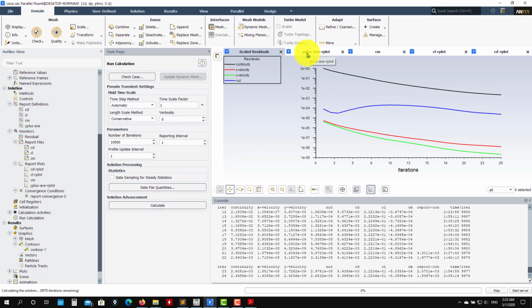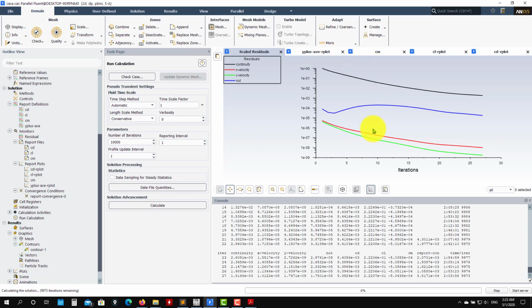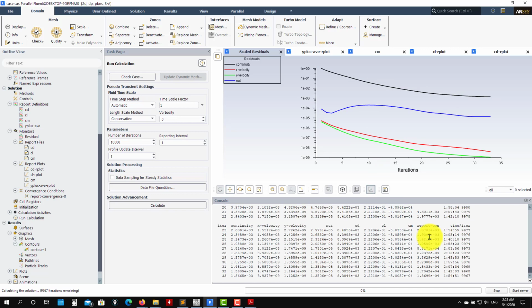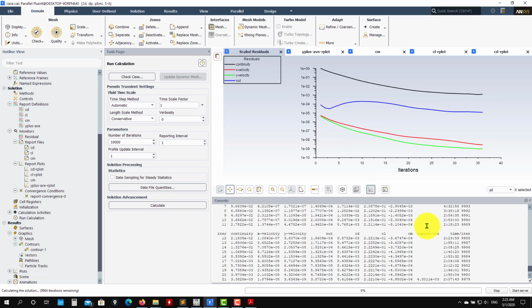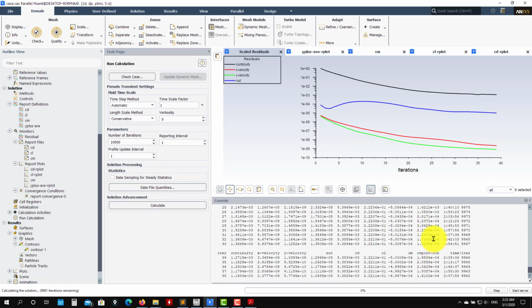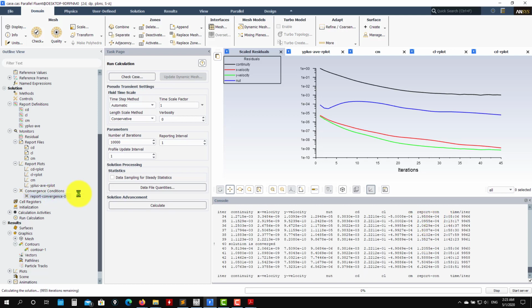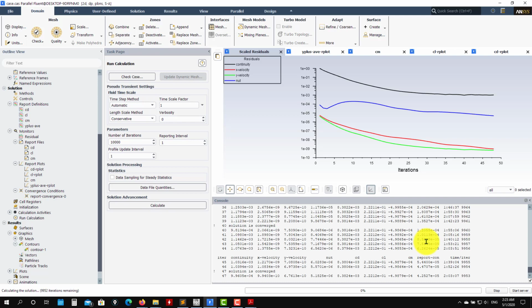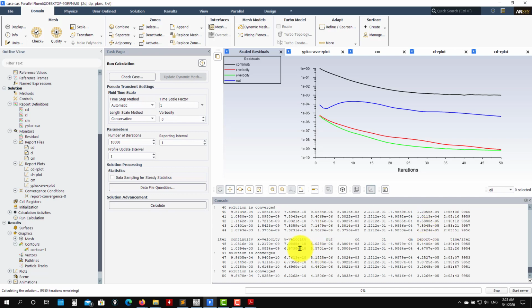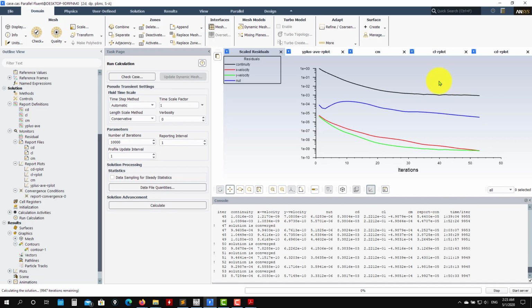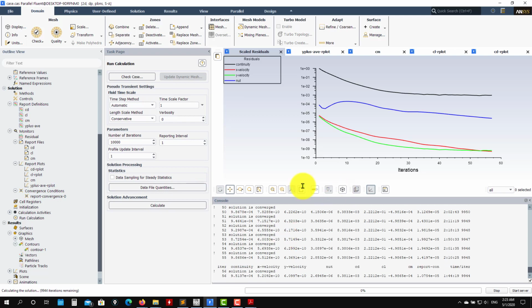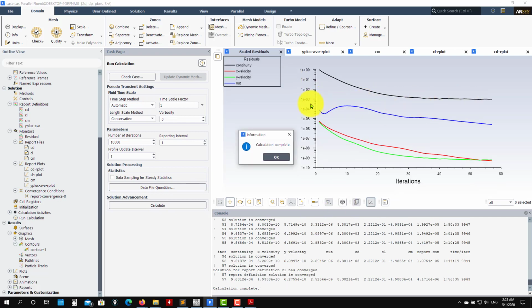And let's wait a little bit. Just to point out, see here that in the first iterations this condition wasn't computed, and then it's been computed, okay? And this is the second convergence criterion that we're using. So see that the solution already converged. This one is already converged, but I still need to converge the residuals. And see that now my residuals converge after 56.